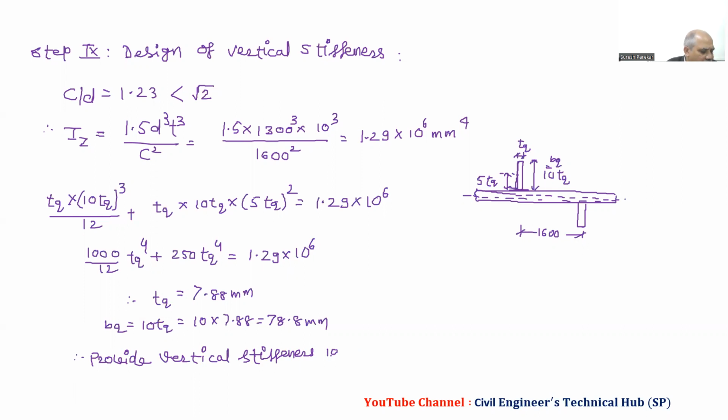We have taken this as 8 millimeter, because we have 7.88, so 8 millimeter by 80 millimeter, alternately at 1600 mm center to center.